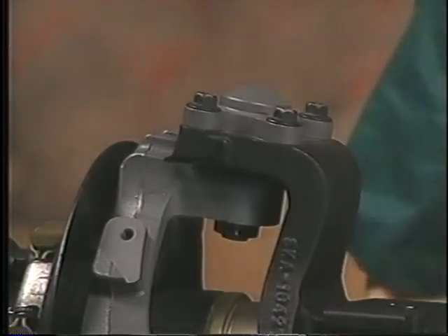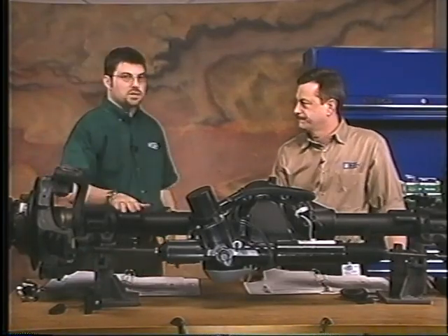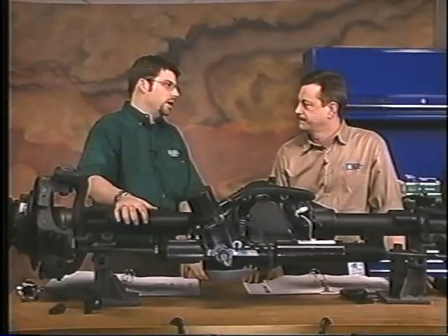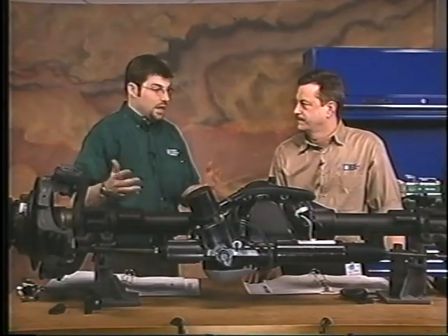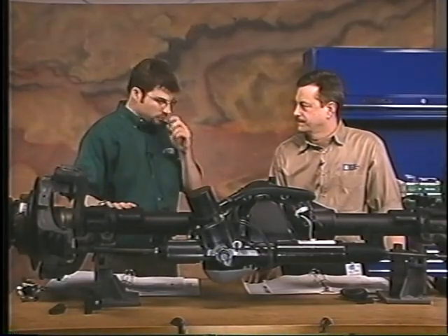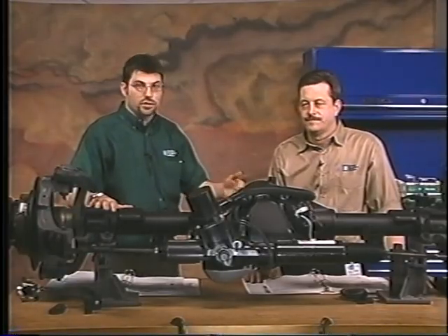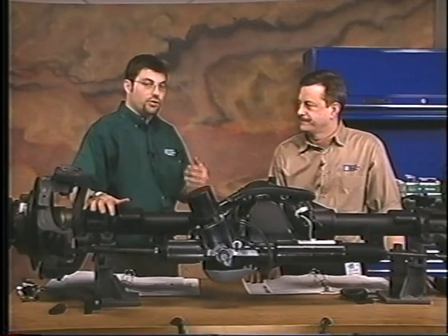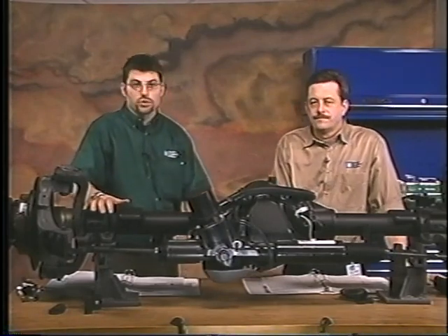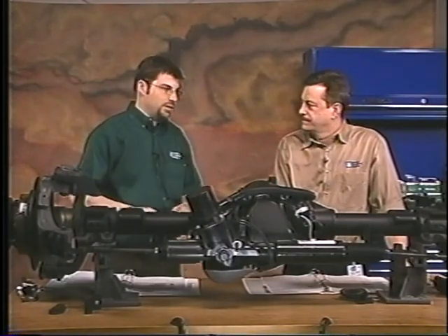All right, we've got to talk about angles, too. The only adjustable angle on the system is toe. Set toe, let it go. Another important point for you today: you can adjust camber, but you can't adjust caster. That's why they also recommend not to shim the pinion to try to change the pinion angle to correct for any launch shudder concerns. Because if you do, you're going to have an impact on camber and caster angles, which are non-adjustable. So we want to keep that in mind too.